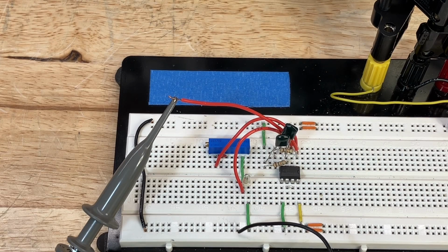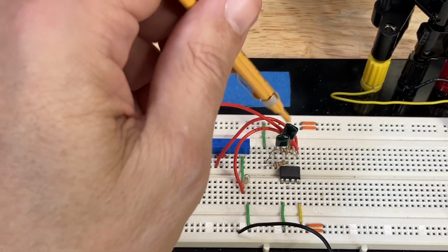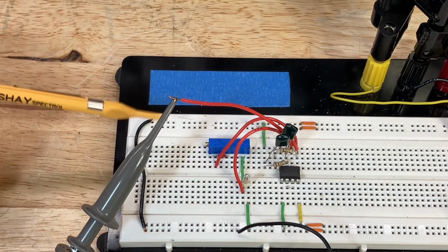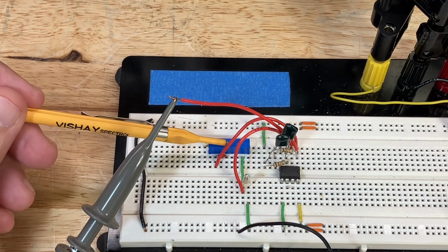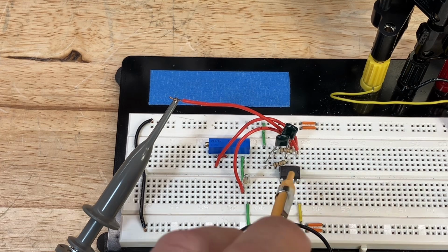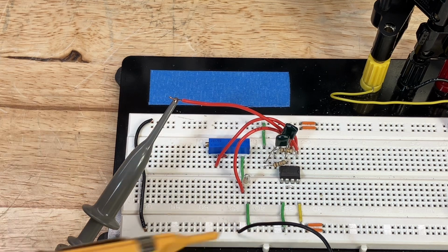Okay, very, very simple. It's exactly the same circuit that we just looked at. I didn't add anything extra. I have a series and parallel RC combination, 10 nanofarads, 10 kiloohms. Here's my resistor, this variable trimmer resistor. There's the light bulb. You might not even be able to see it, but the light bulb is right there. Okay, I stuffed it in there along with an op amp and my scope hooked up to the output, and let's turn it on and see what we get.